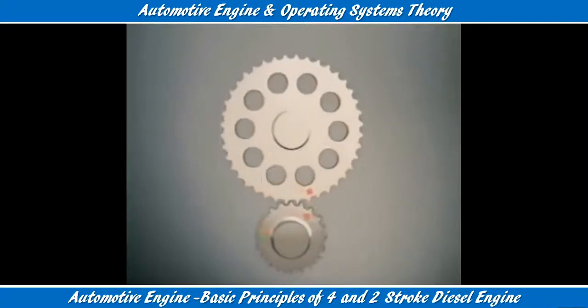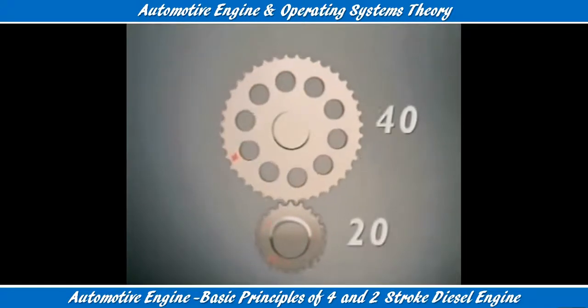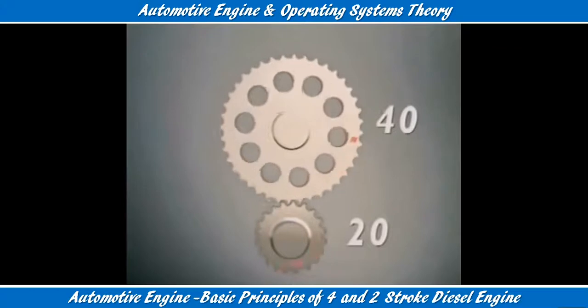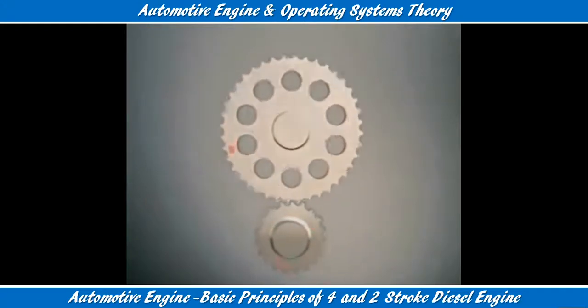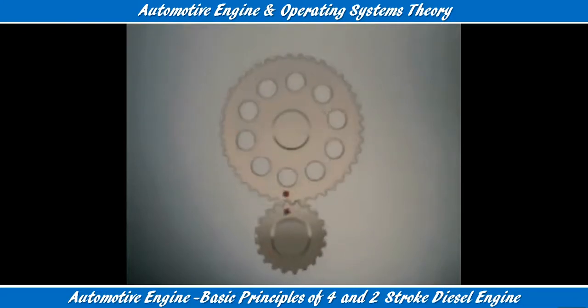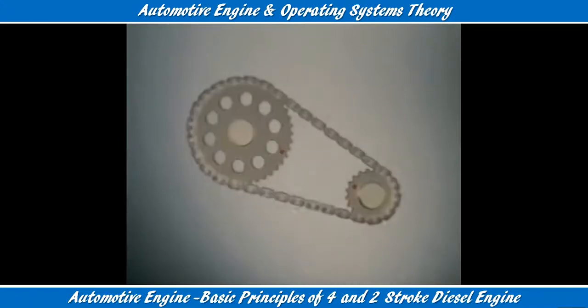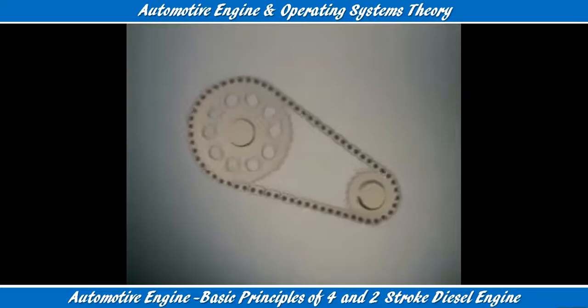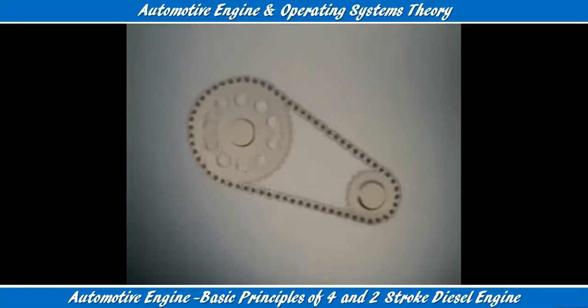Take two gears with teeth the same size, one with 40 teeth and the other, the driving gear, with 20. When they mesh, the larger one rotates at half the speed of the smaller one. The gear with twice as many teeth turns at half the speed of the other. These gears turn in opposite directions, and the one with fewer teeth rotates faster. Now let them be separated but linked by a chain. They turn in the same direction, at the same speeds as when they were meshed.